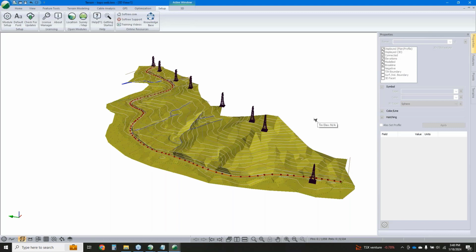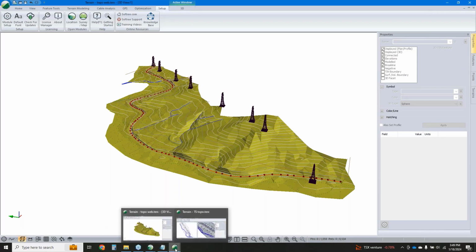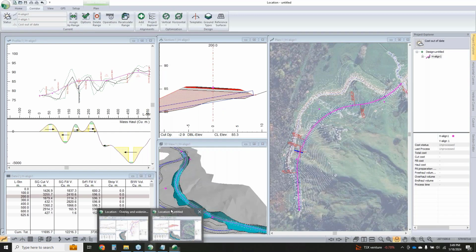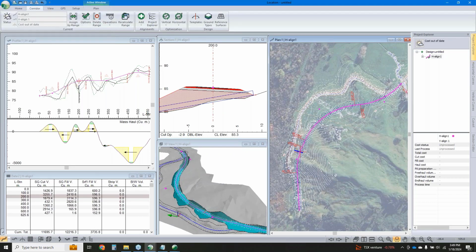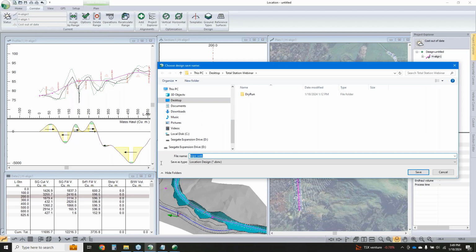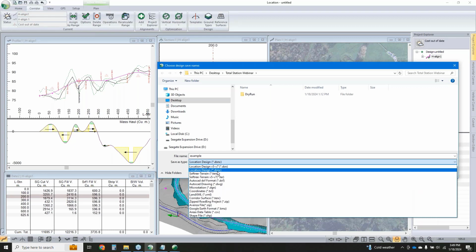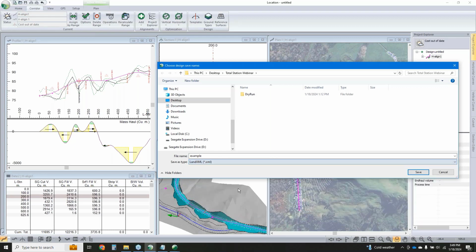Okay, couple more questions. I know we're already over time, so let's see if we can get through these. The next one kind of goes back to the LandXML question area. With exporting a LandXML, in order to bring it into Civil 3D, will that import the alignment, the vertical profile, and the corridor also? Yeah, so maybe rather than just point, I'll go through the next step of looking at that set of options. So file, save as, I'm going to just say example.LandXML.